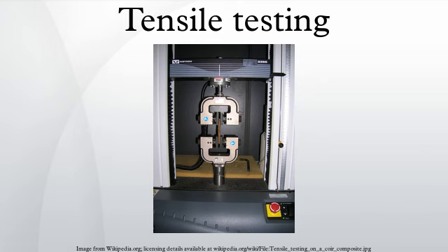The machine must have the proper capabilities for the test specimen being tested. There are 4 main parameters: force capacity, speed, and precision and accuracy. Force capacity refers to the fact that the machine must be able to generate enough force to fracture the specimen. The machine must be able to apply the force quickly or slowly enough to properly mimic the actual application. Finally, the machine must be able to accurately and precisely measure the gauge length and forces applied. For instance, a large machine that is designed to measure long elongations may not work with a brittle material that experiences short elongations prior to fracturing.